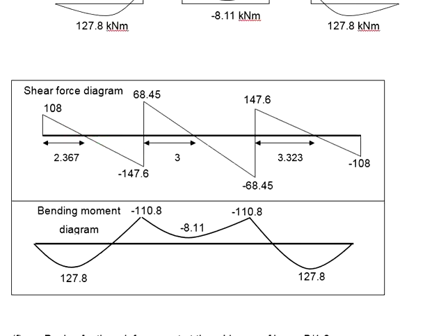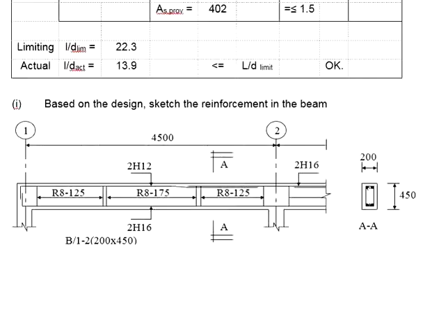What you can do in order to save cost, knowing that the minimum shear link applies, is that whatever shear loads are less than the shear resistance provided by the minimum shear link will use the minimum shear link. For the rest, you will use the maximum shear link to be provided throughout. That will lead to closer spacing of the shear links near the support and larger spacing at the midspan. You can save some of the shear links here. The beam will not fail in shear even though you provide fewer shear links here, provided that the amount of shear link provided here is more than the minimum shear link.